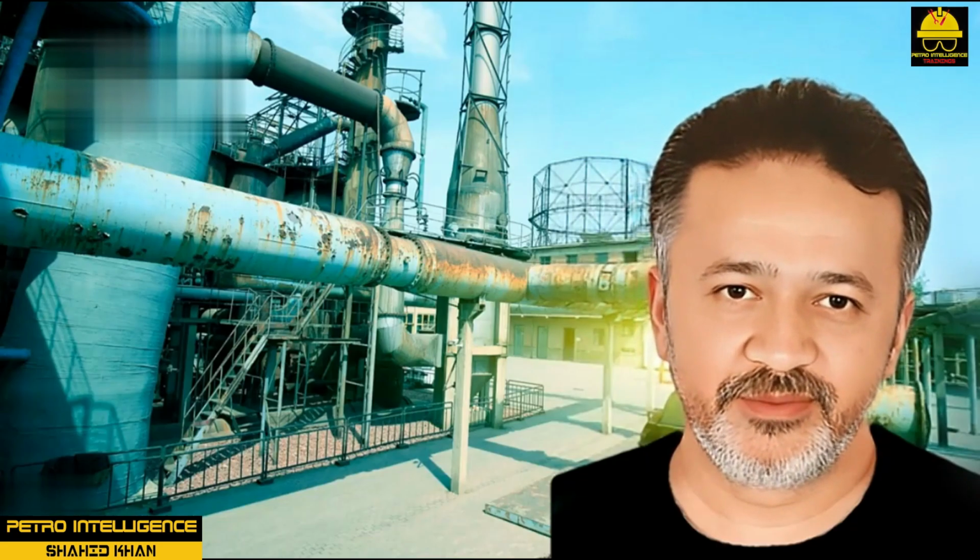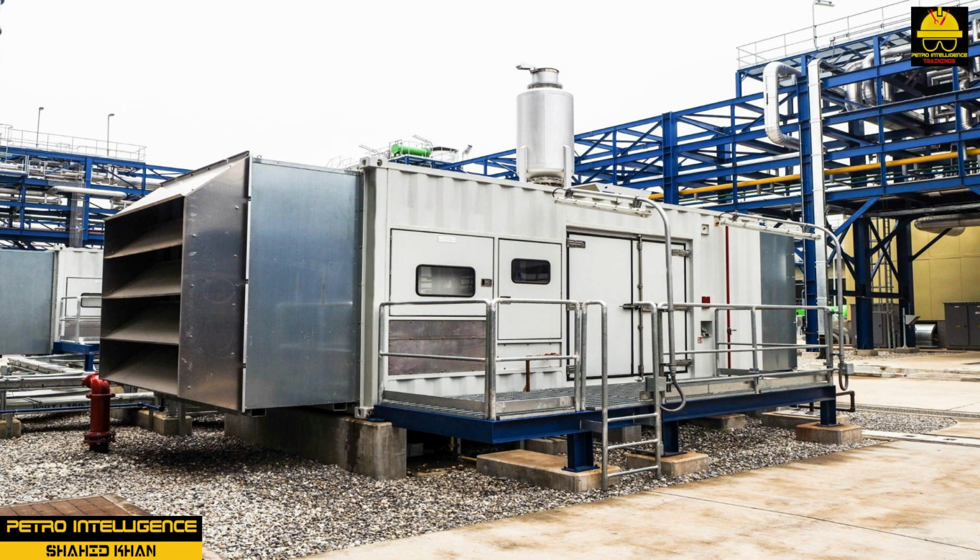Backup power systems. Backup power systems ensure continuous power supply to critical equipment and instruments. In addition to the normal power, an emergency diesel engine generator and an automatic transfer switch provide an alternate source of power. When normal power is lost, the transfer switch delivers backup power from the emergency diesel-driven generator.